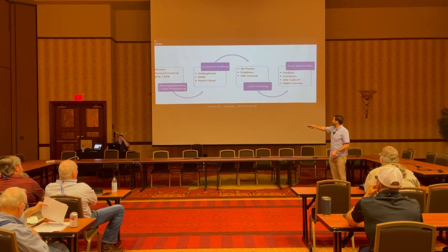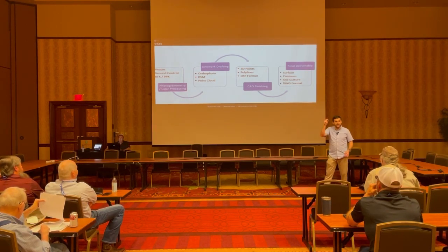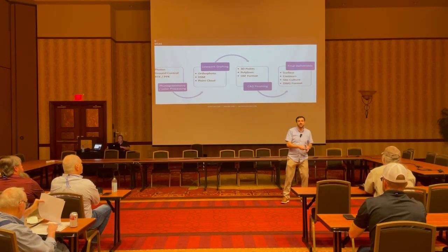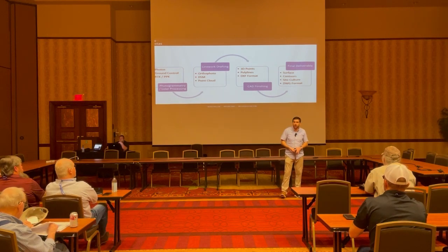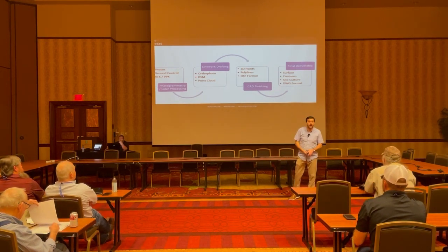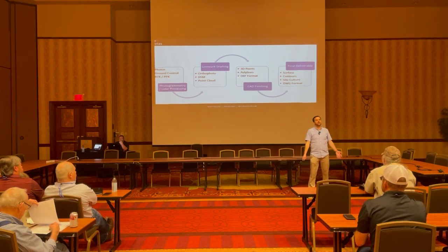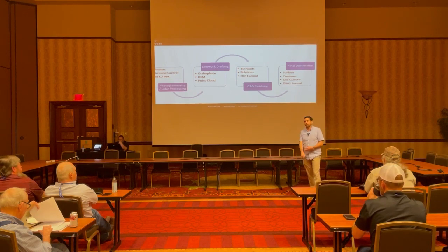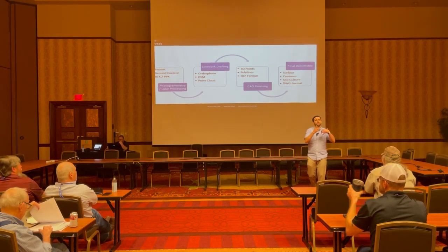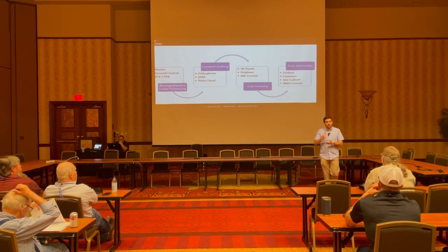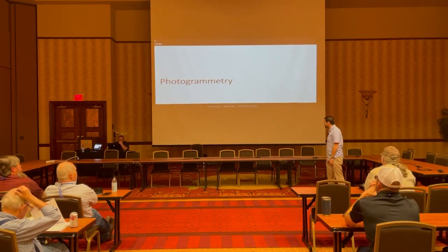It is in photogrammetry. It does not go into line work drafting until we have checked off that it has completed photogrammetry processing. It is not that we do all of this at once and mush it all together. No, no, no. A project goes through a linear step. We don't start line work drafting until we are confident in the accuracy of it, because otherwise that leads to rework, extensive costs, field revisits, all of that sort of stuff. This is the type of structure that a really good drone program needs to get reliable data out of it.